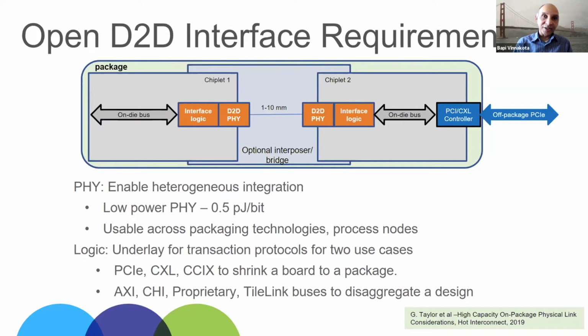Typically, what happens is that your packaging technology becomes more complex when you do that. You almost always need advanced packaging technologies, so it boils down to a choice of how complex. This is one of the really interesting things in my mind in chiplet-based designs. Factors that a designer typically considers way downstream have to be accounted for in the architecture, because if you choose bumps or micro bumps, it's going to determine what your test coverage for known good die is.